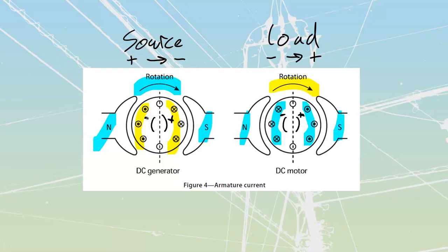because of my field coils, series or shunt types of fields, and in some cases we're going to have compound wound motors. If I have a compound wound motor, that compound motor is going to need to have all the windings changed. If I only change a couple of the windings, maybe my shunt windings, and I don't change my series windings, I'm going to change it from possibly a cumulative compound into a differential compound. It will have a completely different aspect to the way that it operates. So rather than screwing around with which one do I change, I'm usually going to change the polarity of my armature.